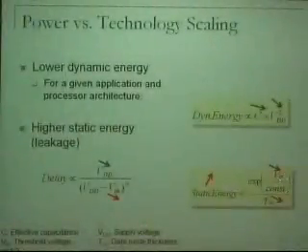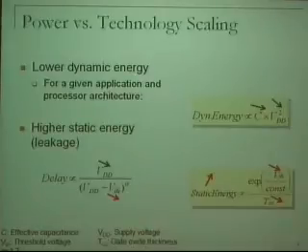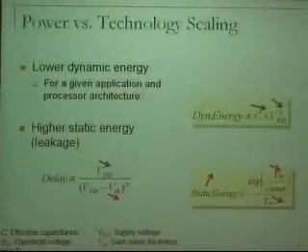This can very effectively control the leakage. It has an exponential relationship, as you see here. So static energy has an exponential relation to VTH. So you reduce it, the static energy is increased very highly. The other knob is TOX, gate oxide thickness. Again, you can reduce this, and you have to do this because you are scaling the technology. So in order to keep your transistor working, you have to reduce the oxide thickness when you also make the transistor smaller. So as you see, static energy is increasing.